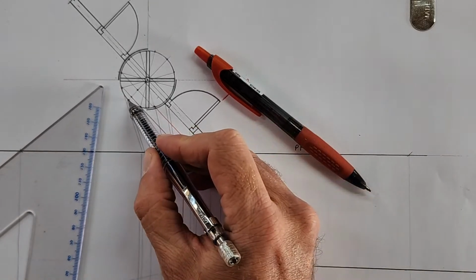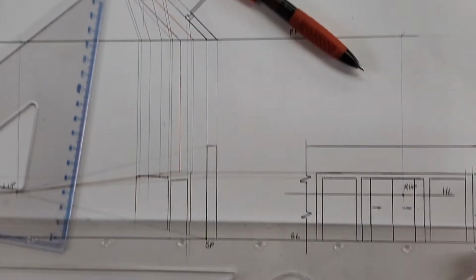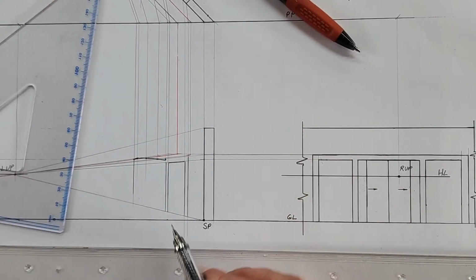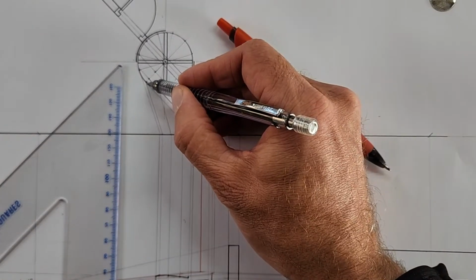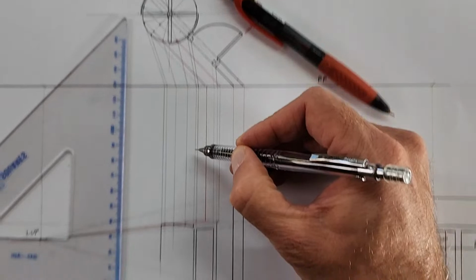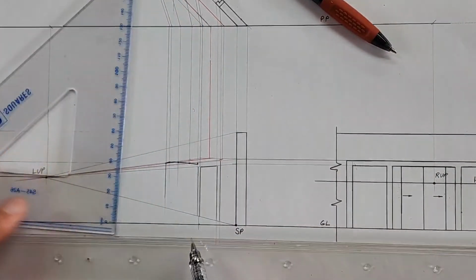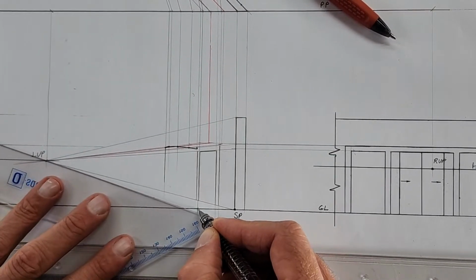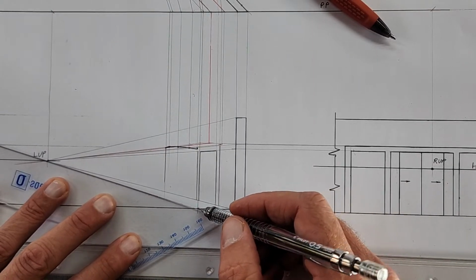Okay, so these drawings, we made these marks now, projected it to the picture plane and down for the top height. We're now just going to bring them further down to the bottom. So we'll do one at a time. We'll start on the front here. There it is, come down. We'll just extend that one now to our ground, and from here back to the vanishing point. Do you understand that, people?